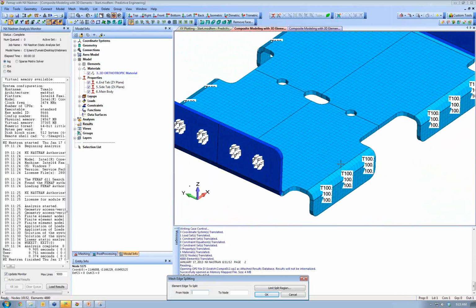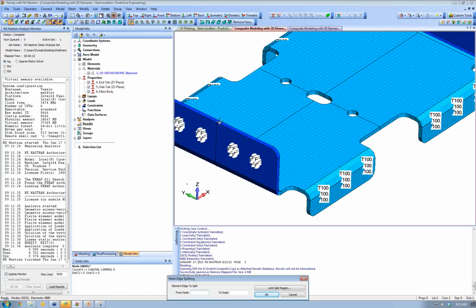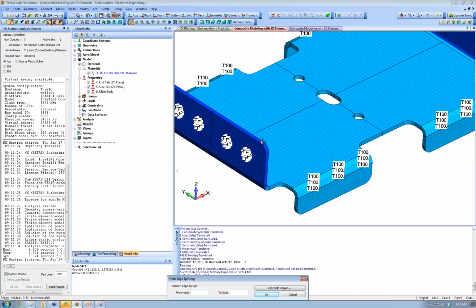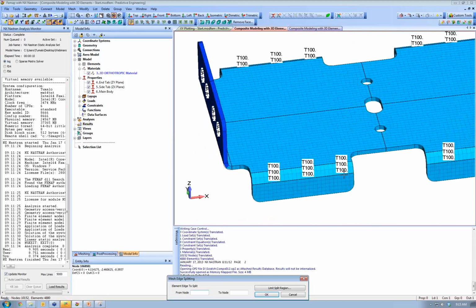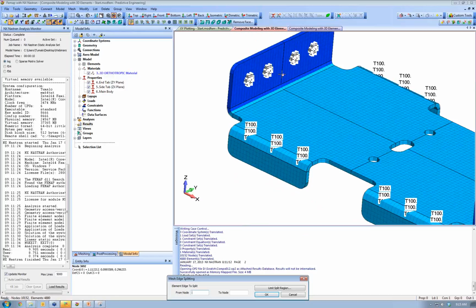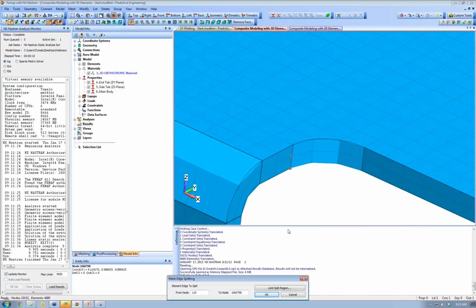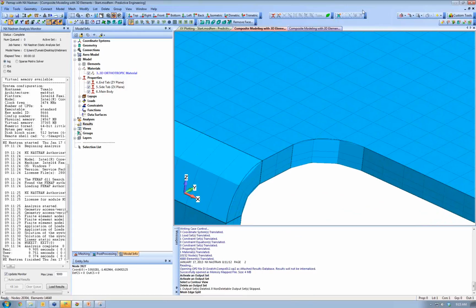If you've done a fair amount of hex meshing, you'd know that to remesh this solid, we would have to resize our element size on each one of these edge curves throughout the entire thing. So this is a really handy tool. Works with plates, beams, I think pretty much everything besides tetrahedral mesh. You want to do it again, just between two nodes, and okay.